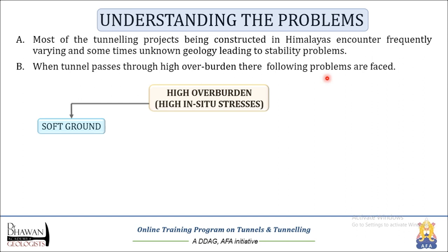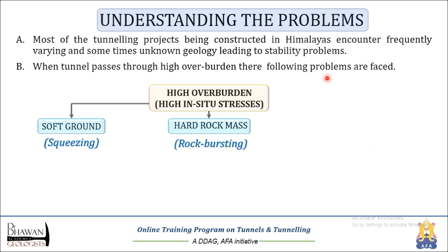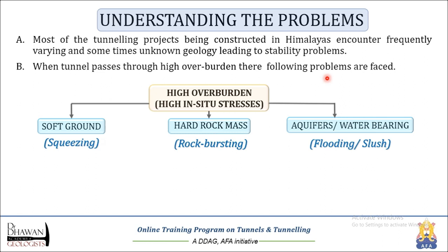And if the tunnel media is soft ground, then squeezing will take place in such a situation. If the tunnel is being excavated in hard rock mass, then rock bursting will take place. And if we encounter aquifers or water bearing strata, then flooding or high ingress of slush will take place.